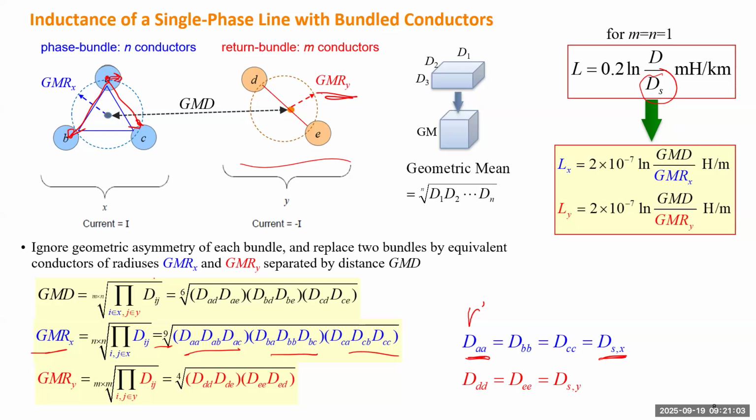So you see, by using this example, we can explain that when you calculate the GMR for each group, you just use each one as a reference. You consider the radius on its own and the distance to anyone in the same group. Then you change the reference to another one. So if I have 3 elements, that will be 3 by 3. A 4 element group will be 4 by 4.